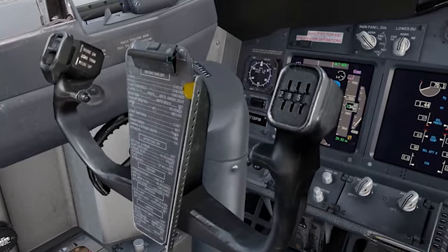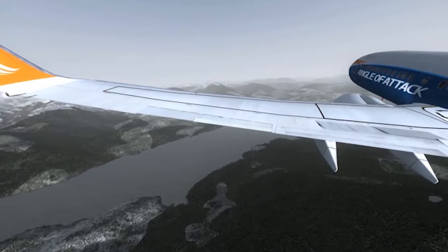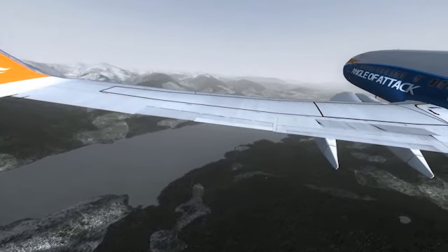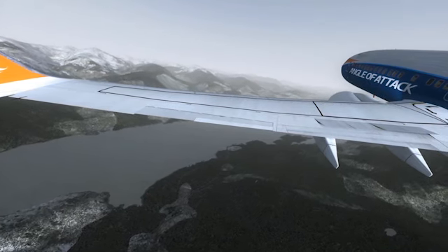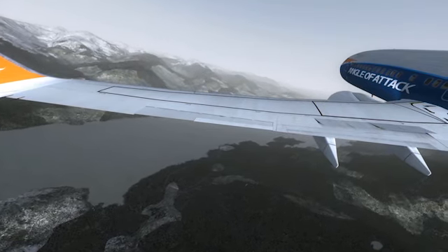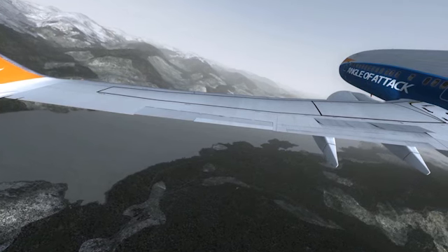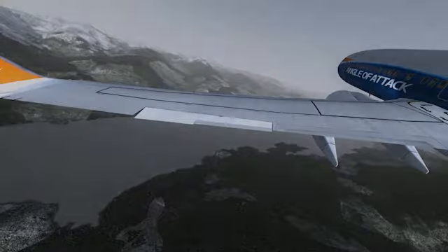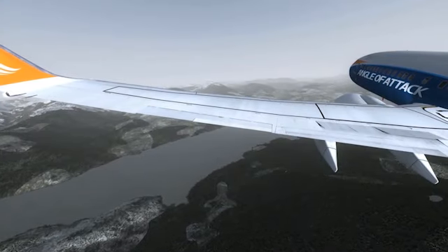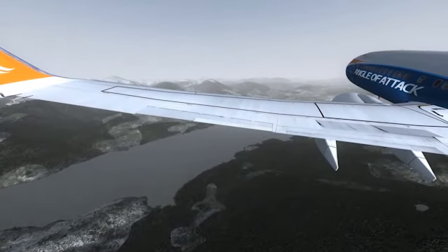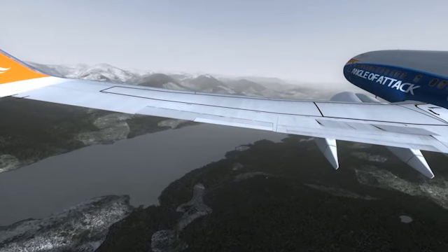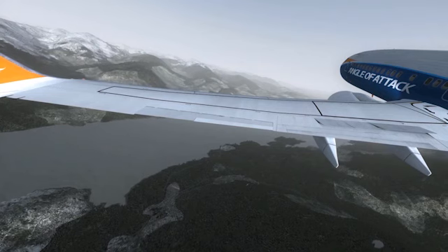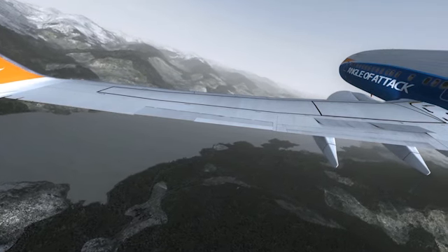position. The captain's control wheel directly transmits force input to the aileron feel and centering unit, whereas the first officer's control wheel directly transmits force to the spoiler mixer. The spoiler mixer is further discussed in the secondary flight controls lesson. In case there's a failure or jam in either control wheel, the aileron transfer mechanism allows for both control wheels to be able to make roll commands.